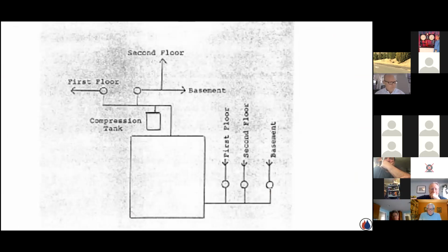I guess we'll talk real quickly, we'll get into flow control valves. A gentleman sent me an article, sent me a picture. He was having a problem, and he had a 2-story home, 2 zones, first floor, second floor, a flow control valve, and then 2 circulators, first floor, second floor. The family does the basement over. They created a family room. The plumber comes in, puts in a third zone in the basement, and puts the pump on it right here, adds to the manifold, and taps off of this T here to feed the basement zone.